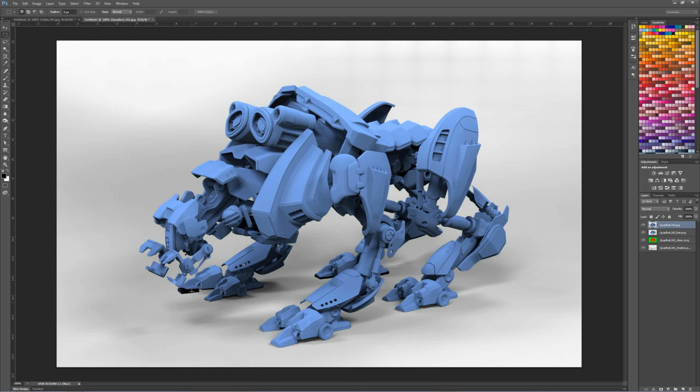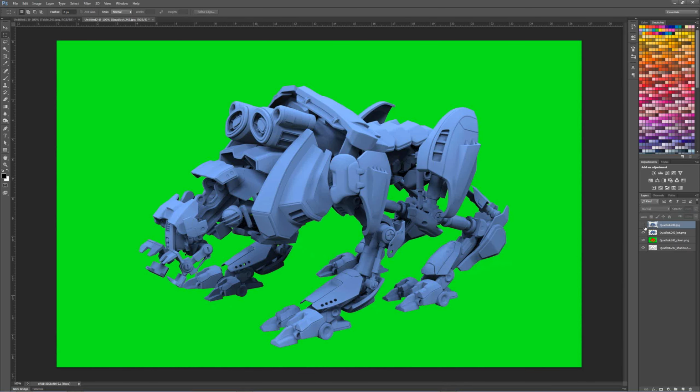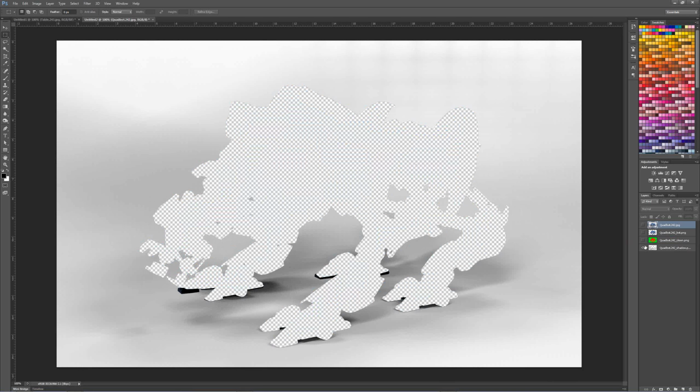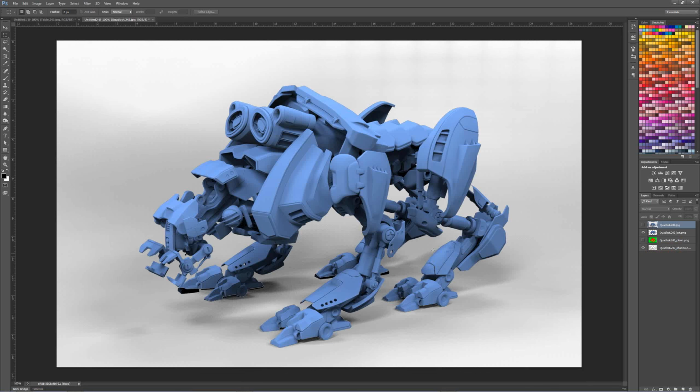You can see that that backdrop had a curve to it, so that's why you're seeing the black on the feet here. But if we hide the final render, hide the clown pass, you can see that the model was separated from the shadow, and that was by using the render layers, putting that backdrop ramp onto its own render layer as well as the bot. So if we move this to the back, we'll get rid of the white fringes there.